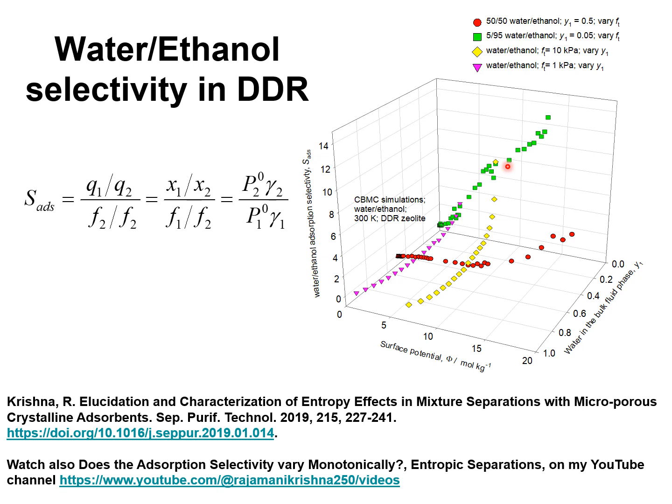And this is of vital importance for permeation of water ethanol mixtures across pervaporation membranes, because in the hybrid scheme for distillation combined with membrane pervaporation, the mixture which is rich in ethanol and poor in water is sent to a membrane pervaporation unit, and since the mole fraction of water is smaller than, say, typically about 5%, the adsorption selectivity is in favor of water.